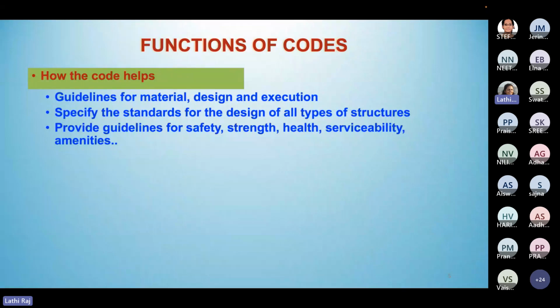But IS 456 2000 is giving you some of the new materials in cement, which is fly ash cement, which is added. That is PPC. Okay. PPC also is included in IS 456. That is why SP 24 is withdrawn, because it was not giving you any idea about those new materials in construction, based on PPC and other types of cements.